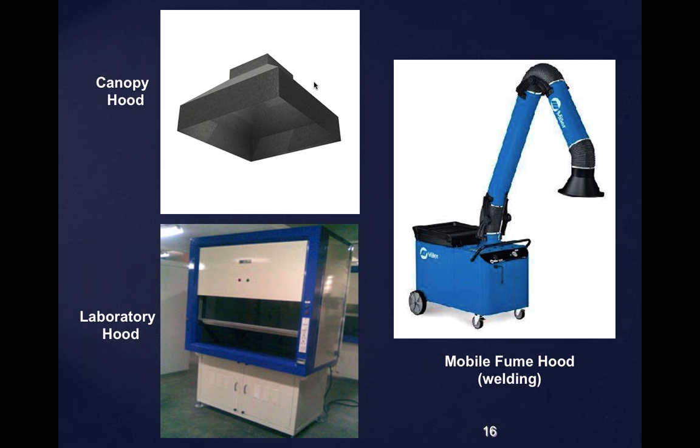If there's a fire, that plug will melt away, and the blast gate will drop down and block the flow of air. That's literally just like a blast gate, a piece of heavy sheet metal that drops down and blocks the flow of air. But we don't usually see blast gates in HVAC systems for adjustment.